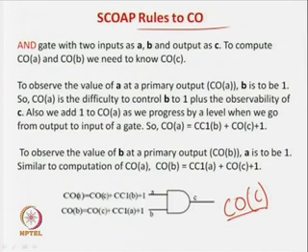Now, say you know the difficulty of observing this line. You need to find out how difficult it is to observe this line at the primary input. To traverse the fault effect from this one to this one, we need to apply a 1 at B, correct. If you apply a 1 at B, this value can be forwarded to the output, correct.